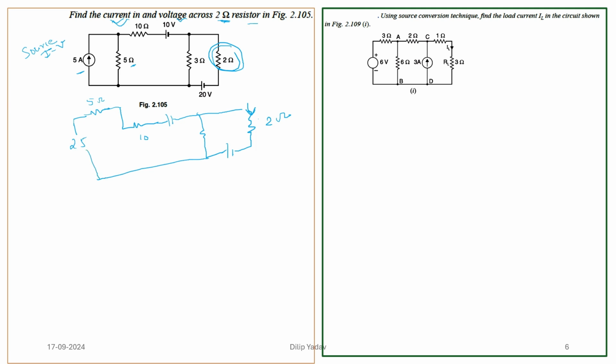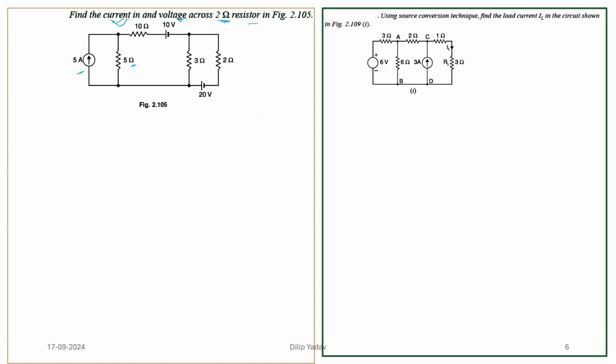Because I can calculate the values of I1 and I2 directly, how are we going to solve this? We are going to take the two loops again with a source transformation, from the current source to the voltage source. By transforming it, I am going to make it a little less complicated so that I can calculate the values, because the two loops I can easily solve.